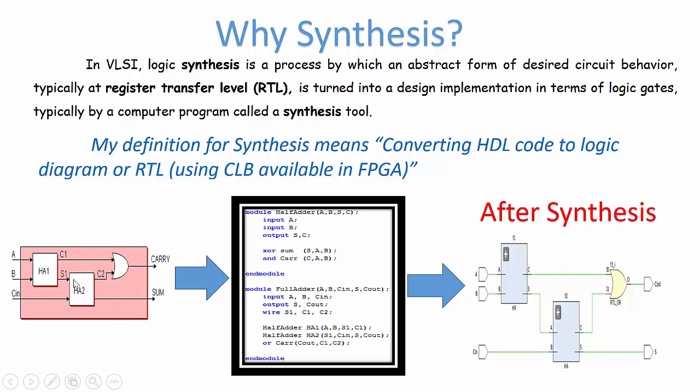Here is one example: by seeing the logic diagram or truth table, we write the code for a full adder, and after synthesis you get a diagram like this. In this case, the logic diagrams are the same. But if we go to a counter program or any other programs, the original logic diagram and the synthesis diagram will not be equal.